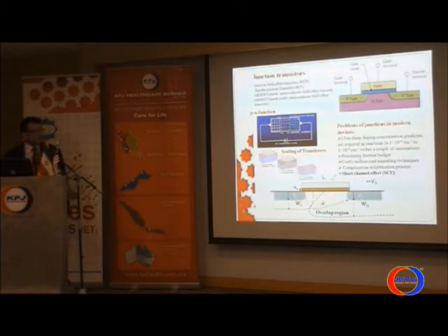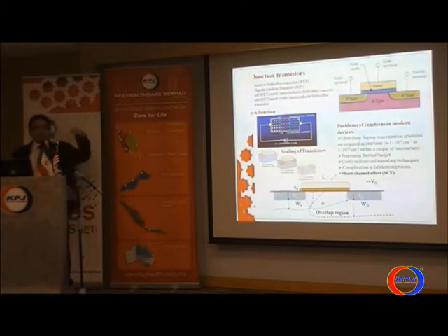When these two junctions get close to each other, we get this overlap problem. Shortly, we call it short channel effects. This is the problem of the junction in modern devices. First, ultra sharp doping concentration. Doping means we need to deposit a lot of charge here, because when the size gets smaller, we need extra charge to have carriers. So we need to deposit and dope the charge into the devices.